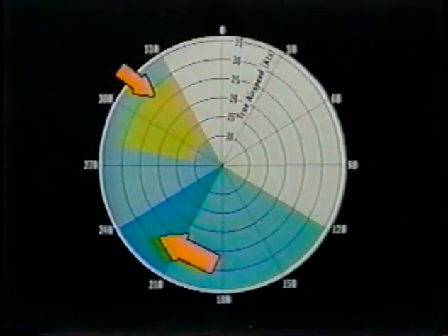It is important to note that there are two areas of overlap. Control of the right yaw rate is critical when flying in either of these areas. The pilot must be aware that left pedal application is critical to prevent a right yaw from progressing into a spin.